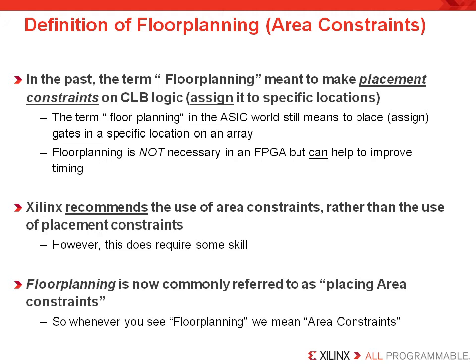In the ASIC world, floor planning means to place gates in a specific location in a gate array. This terminology has been borrowed by FPGA users, which means to place CLB logic in specific locations. As such, floor planning is not needed in an FPGA. But you can floor plan your design if it does not meet timing.